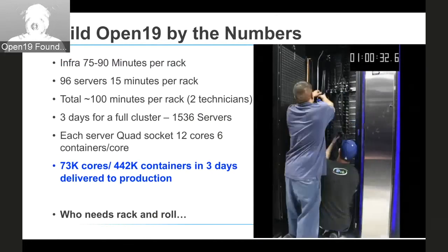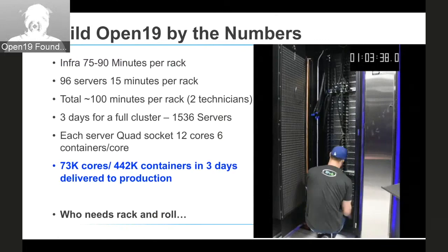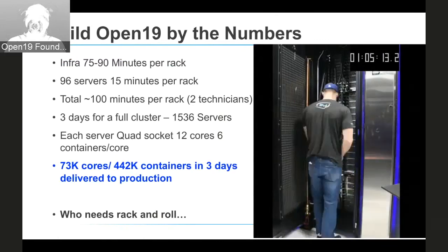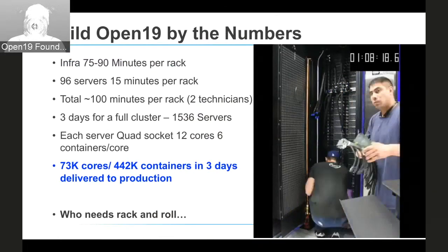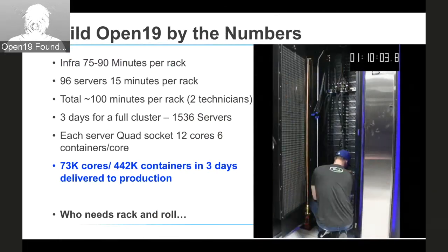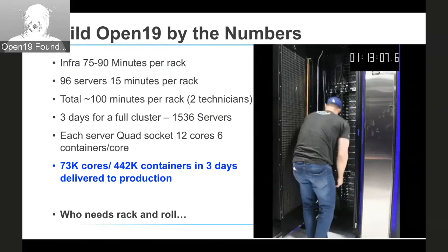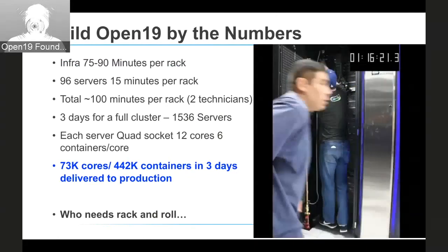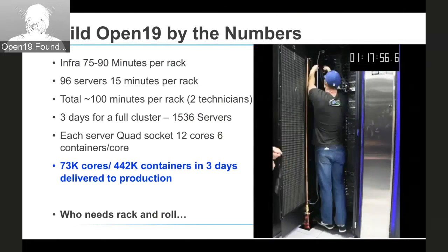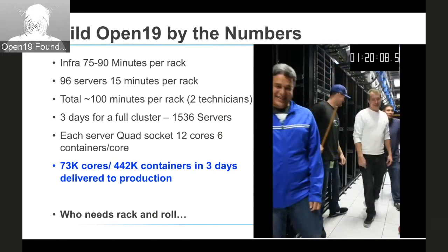What you see the team doing right now is installing the cables on the back for the snap-ons. You can see them snap into the back of the cages and preparing them to create blind mate, as well as dropping the whip cables from the ceiling, connecting the power into the power shelves and driving them into an active infra. The next step over here is to plug in servers, but as you can see, this is the first build, an hour and 20 minutes.